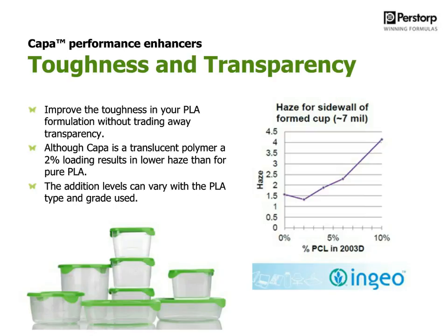You eliminate problems with cracking and brittleness in the production, and also over time it makes the product much more stable when it's stored in cold environments. So this is really interesting and something to consider even for transparent products. So you get both toughness and transparency when adding it into your formulation.